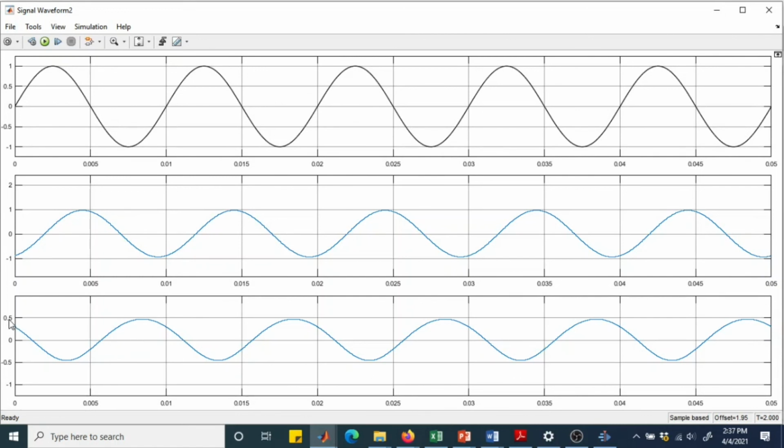Moreover, you can observe that we have the peak value between plus 0.5 and minus 0.5, so we can give a gain of 2 to eventually get a plus 1 and a minus 1 kind of oscillation. So in a nutshell, if we give appropriate DC offset to the message signal, using envelope detector or any other non-coherent modulation demodulation scheme, we can actually recover back the original signal.